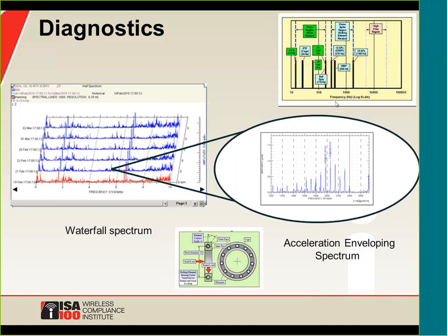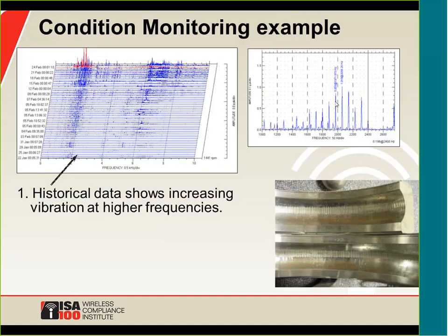And a key analytic tool is acceleration enveloping. That enables you to significantly reduce those frequencies that are not of interest, and allows you to focus on those that are of interest, that are true indications of bearing health.